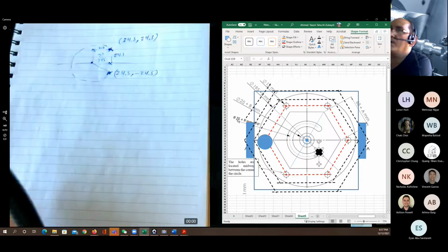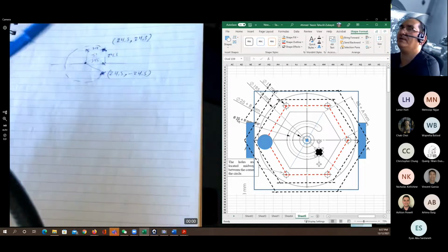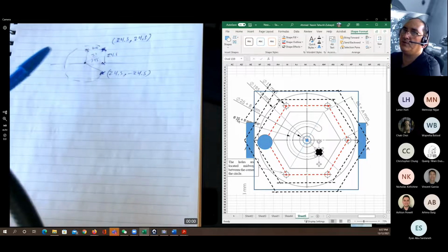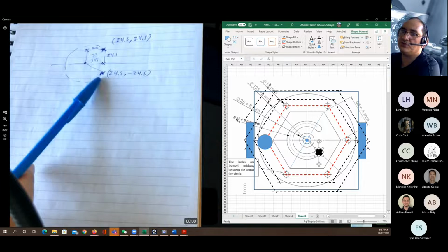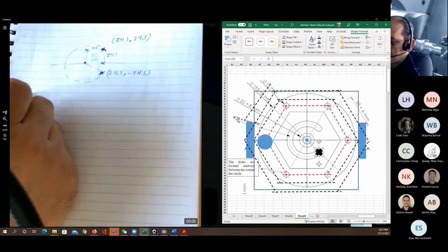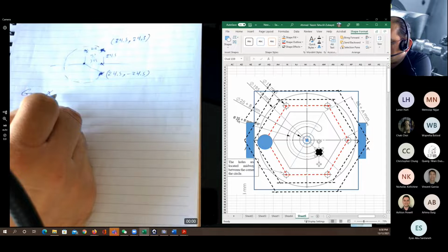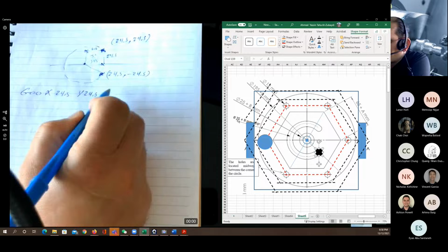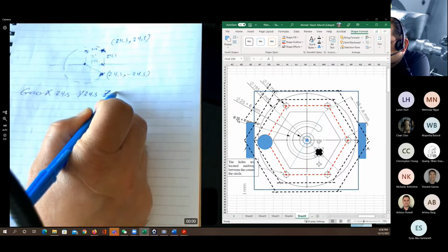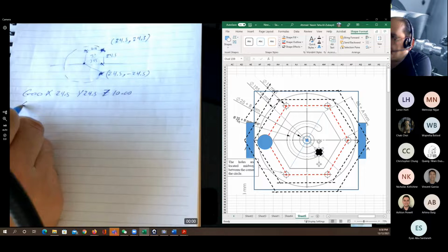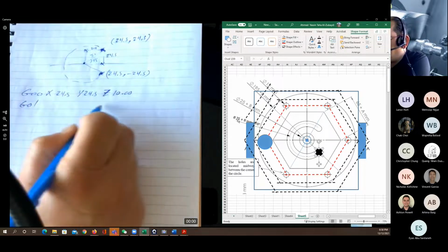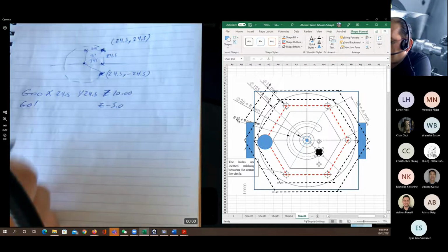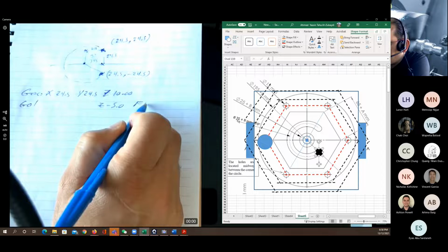Okay, so the only thing we need to do is bring the cutting tool to this location, drill the hole, and then make the G03 in that case to this position and leave. So G00, X 24.5, the Y is 24.5, and the Z once again is going to be 10 millimeters. G01, the Z to, let's say, -5. Okay, and the feed rate needs to be specified.